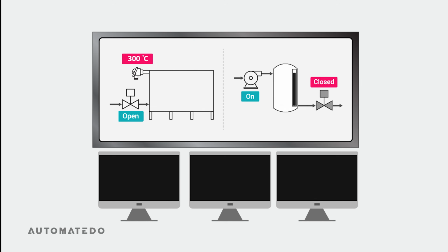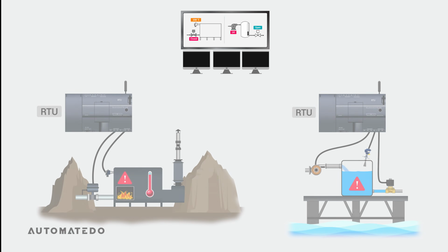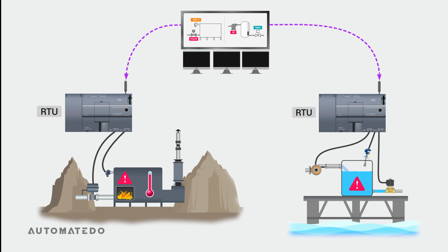Once the control station receives data from the entire fleet of RTUs, it brings all information together and presents a detailed description of what's going on at each site in a single easy-to-use interface. You can use the dashboard to take appropriate actions based on the existing alarm situation on industrial sites and start sending control commands over the communication network to RTUs. Then, remote terminal units will deliver command signals to field equipment to control functions and physical states of actuators, and as a result, fix the issues of local processes.